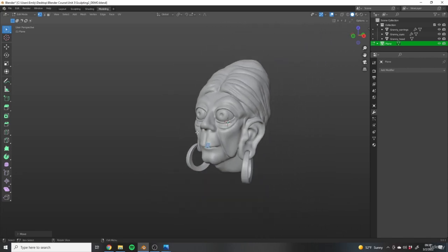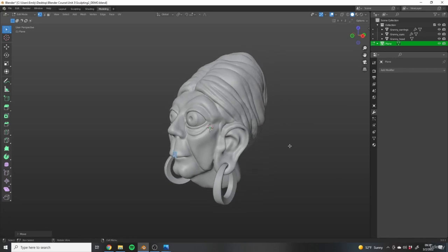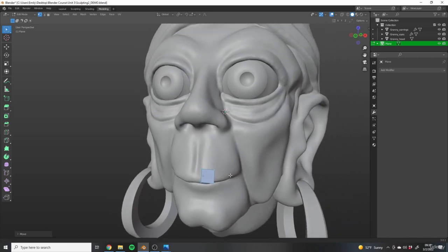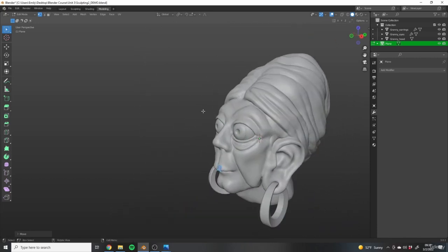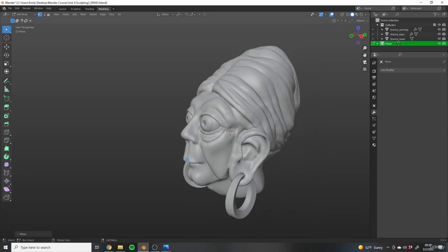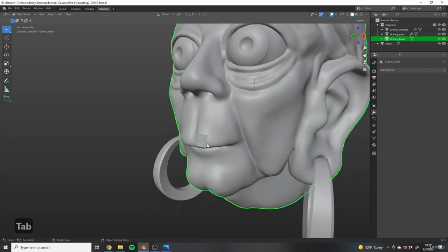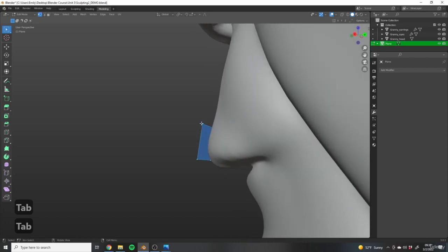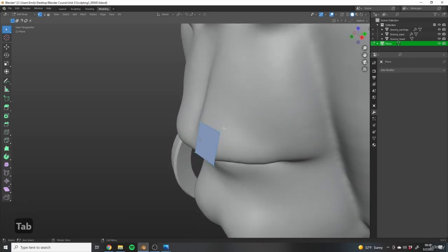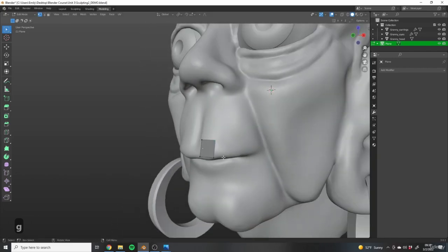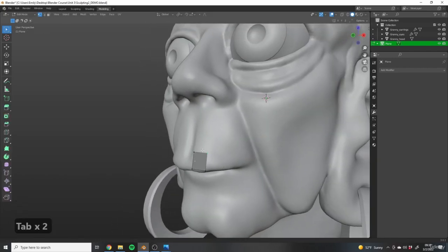Now, there's a few more things we need to do that are going to make this process a lot easier. Retopology is one of those very tedious, time-consuming processes, and you will quickly find that you may want to speed up the process wherever you can. So, just a couple things to start out with. We have this plane here, but right now these points are floating away from our mesh. And rather than having to grab each point individually and move it to the surface, we can automate that process by turning on snapping.